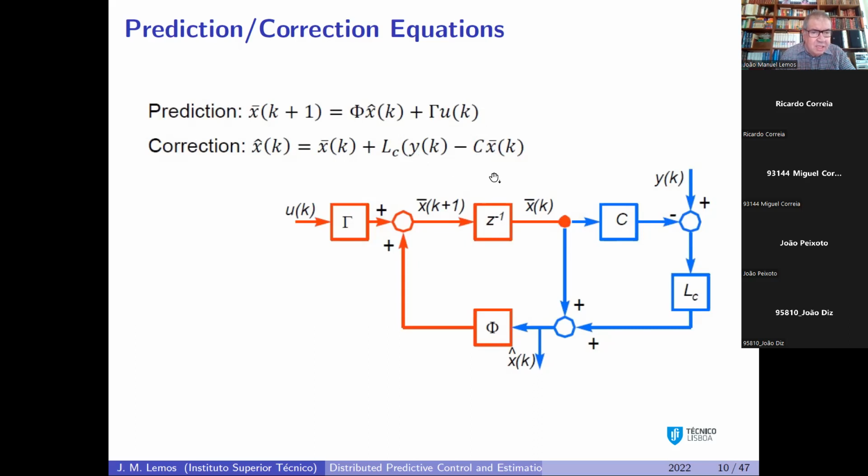And you can represent these equations according to this block diagram where z minus 1 means a delay, and all the rest means the symbols that appear there. This is quite practical for implementing these equations in, say, Simulink, for instance.